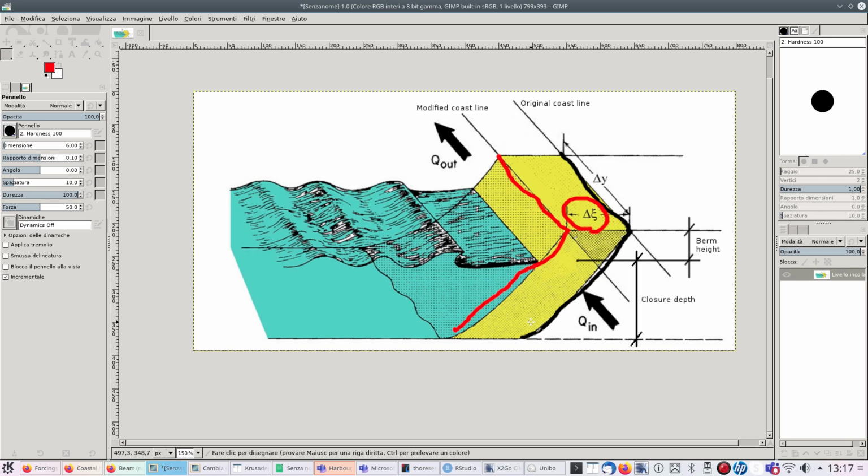It's the difference between a longshore sediment transport in adjacent pieces of coastline. We can estimate the yellow volume, and we can then estimate the delta epsilon. The delta epsilon may be negative or positive depending on the considered piece of coastline. And as a result, the shape of the coastline in each individual piece is unchanged, the profile is unchanged, but delta epsilon will be different from one piece to another, and therefore the overall shape of the coastline will become different.